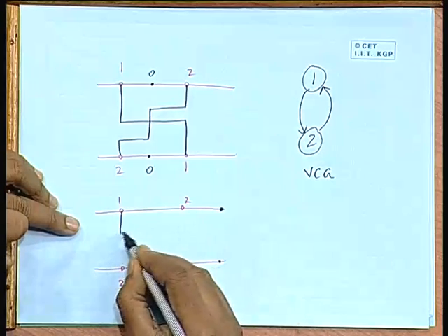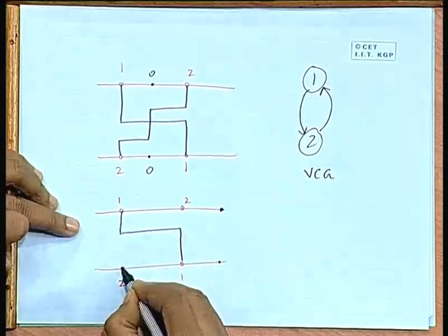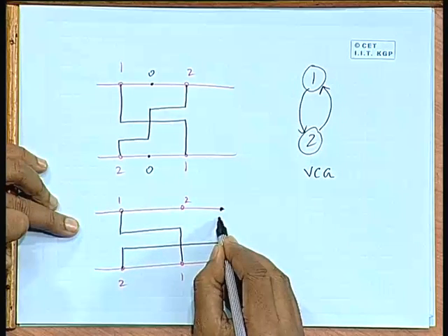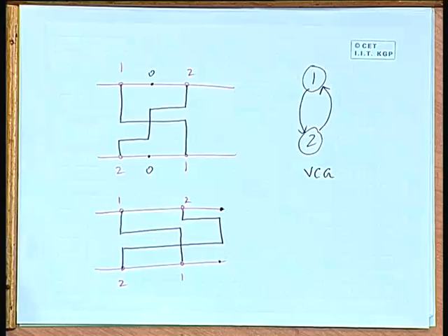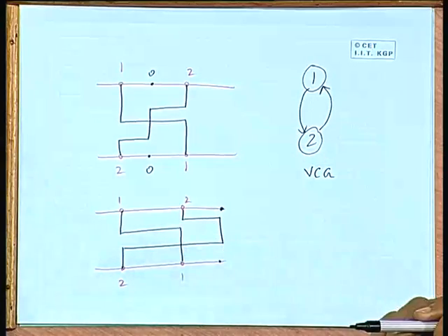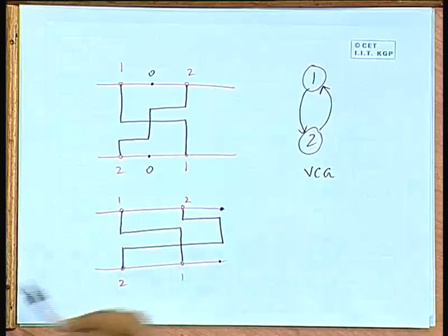So, there what you do, you complete this routing, then net 2 you will be going to this column, then again you will have to come back on another row. So, you will be needing 3 tracks anyway, in both cases. So, the idea is that if you have a cycle in the VCG, you will have to break the horizontal segment of at least one net into more than one track. Okay. So, this doglegging algorithm we will be discussing in detail in our next lecture. Thank you.